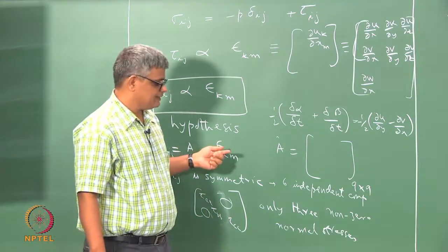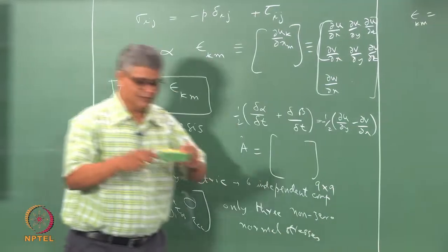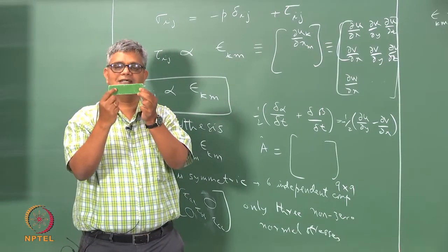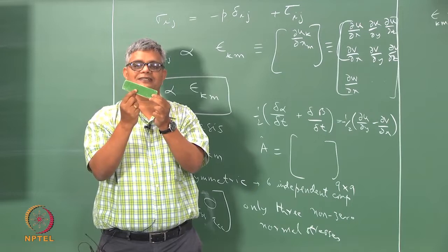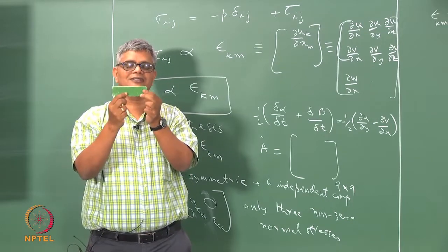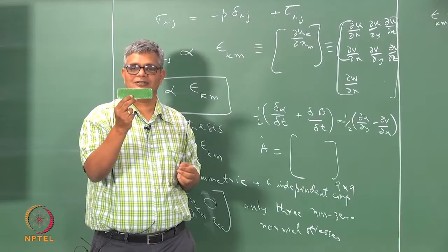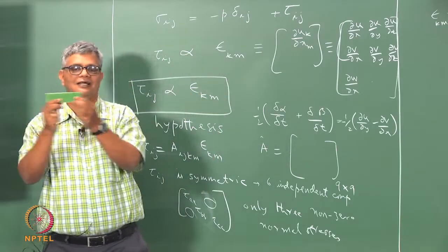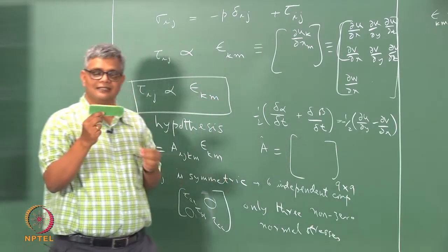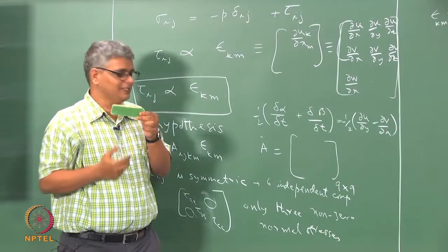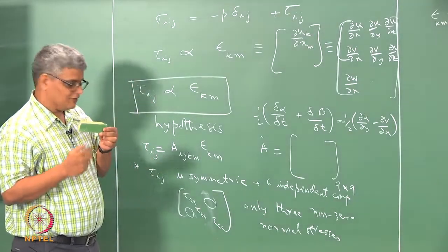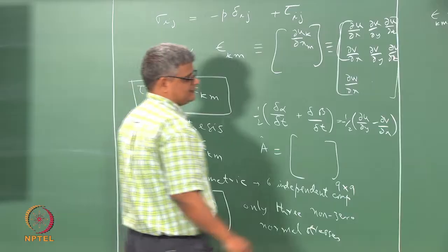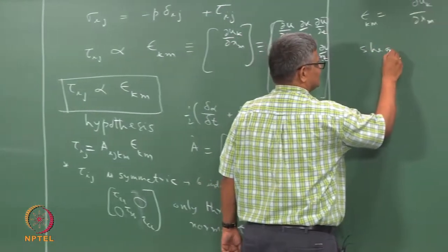Okay. Now we have said earlier that if there is a pure solid body rotation here, the shape remains always rectangular and there is no deformation in this. So you could say that pure solid body rotation does not give rise to any change of shape, it does not deform the rectangular element. Similarly, pure translation will not deform this. So the only thing that is actually changing the shape and thereby creating a strain on this is the shear strain rate and the extensional strain rate.